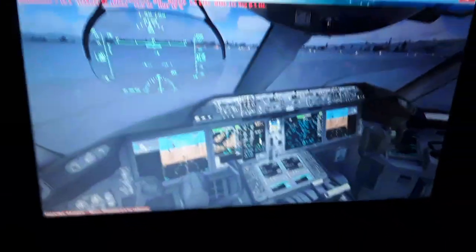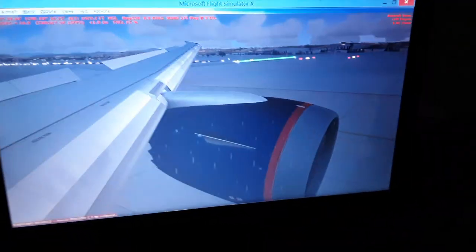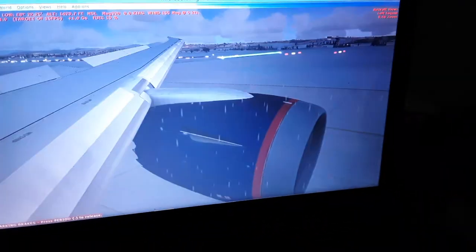we're going to be using thrust of 60 or 70% approximately for approach and landing. So we're going to be touching down with 9 degrees or less. So we're going to have the full flight over here, full manual flight. You're going to see in the other part of the video after I set up the flight management computer and the engines start.